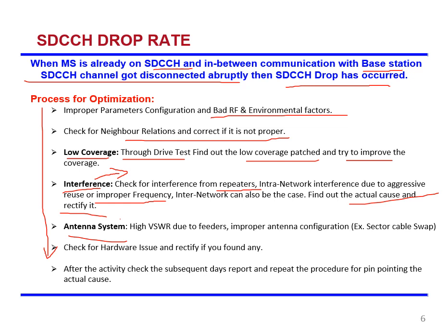Antenna system. Even if the power is good, but the antennas are not radiating properly, it is definitely a cause of high VSWR. What is VSWR? VSWR stands for voltage standing wave ratio. If the VSWR is more, it indicates that the radio frequency power you are transmitting through your waveguide or the RF cable from the source is not being transmitted properly. It is being reflected. Some of the signal you are transmitting is getting reflected back. There is an impedance mismatch between the source and the antenna terminal.